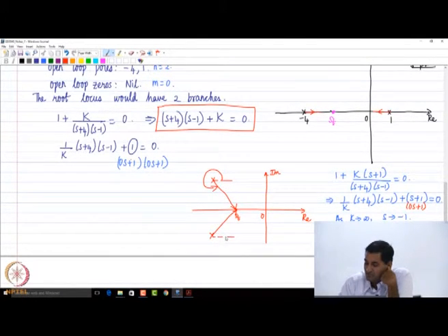What is the angle contribution from this test point? It is this. So, what do you think will be the sum of the angle contribution of these two vectors? Depending on how you look at it, either they will cancel off, or it will become either 0 degrees or plus or minus 360 degrees, right. So, depending on how you count, right. But certainly you see that it is not going to matter as far as locating points on the real axis is concerned.